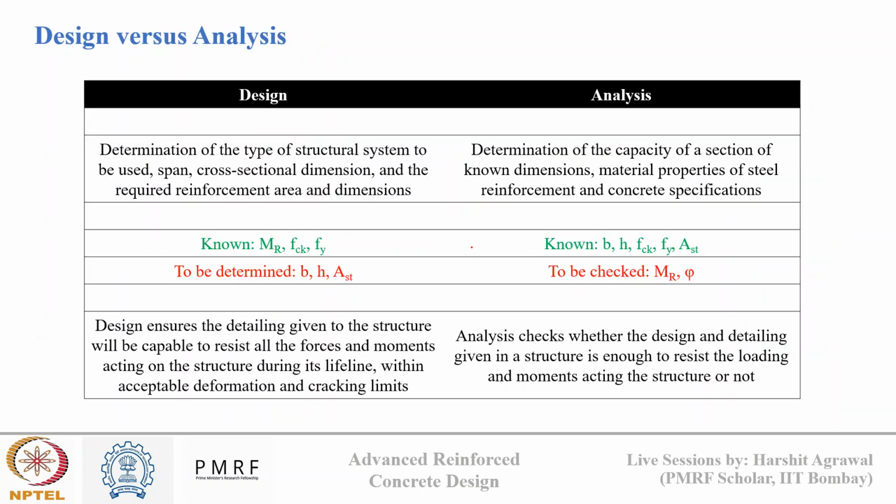Now, coming to the last segment of this session, we will see what is the difference between design and analysis. This slide just compares design and analysis of reinforced concrete. So, what do we mean by design? Design means determination of type of structural system to be used, the span, the cross sectional dimension, and the required reinforcement area and dimension.